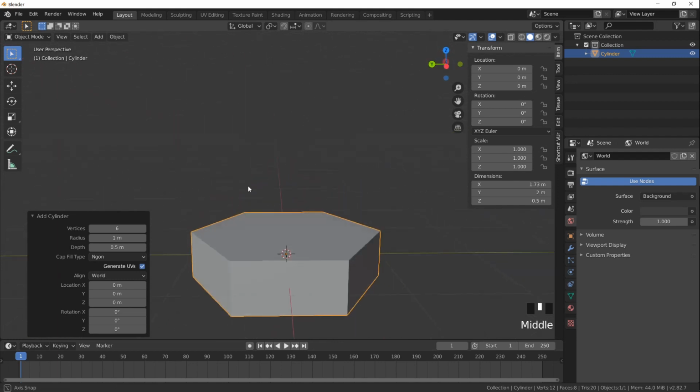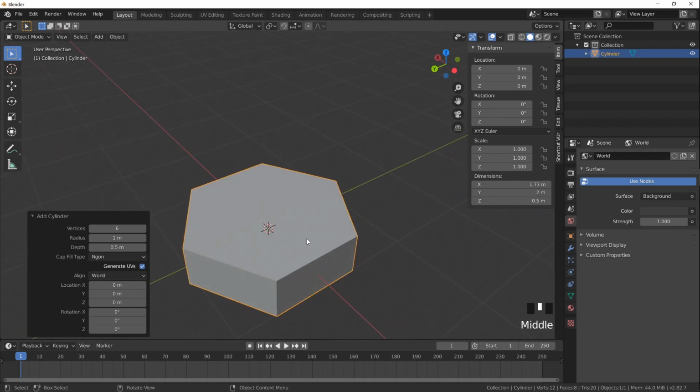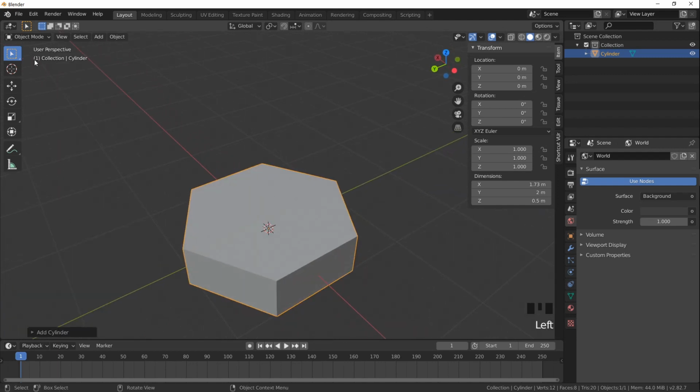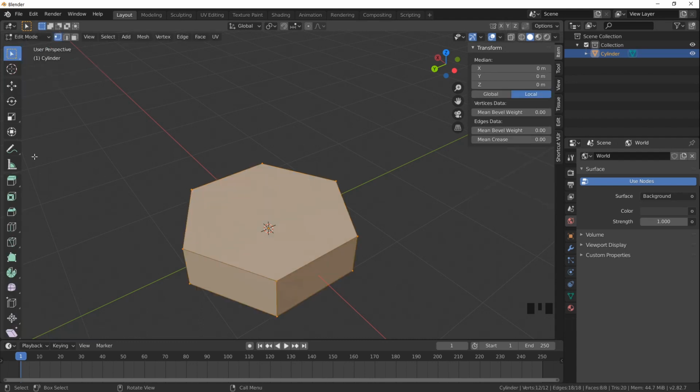Now, if you have created your primitive and you are ready to edit this object, you have to select your object and go from here into edit mode. Now that we are in edit mode, as you can see, the tools here on the left are different. We have many more options and different tools for interacting with the geometry. We can choose if we want to select the vertices, the edges or the faces, that basically are the elements that define a generic mesh object.